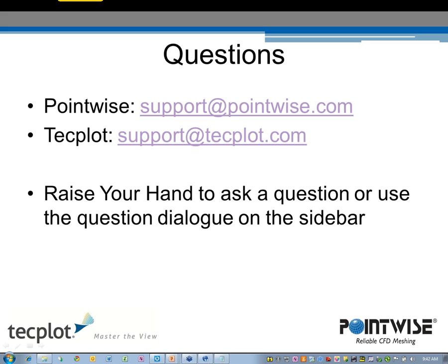Travis, another question for you. In your study, did you validate the baseline case before moving to the optimization? I validated it in the sense that I compared the trend with the trend of a similar wind turbine. Because this was done in 2D, I couldn't really validate a 2D wind turbine. So I simply compared the trend, and the trends were almost identical in that there is an optimum tip speed ratio, and as you move away from that, the coefficient of performance drops off on either side. So that's the validation I did for this case.